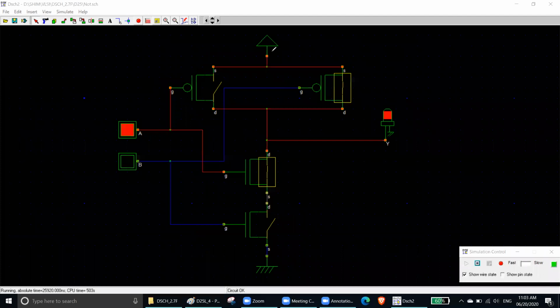See, a current will come. Now it cannot go in both ways because this way is off. So it has to go in this way. Then it will go here, it will go there, it will come here. After that, it cannot go to the ground because this way is broken. So what it will do? It will go through the LED, then it will go to the ground. So by that moment, your LED is on, that means your output is 1.